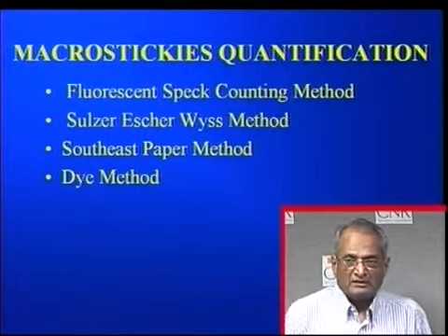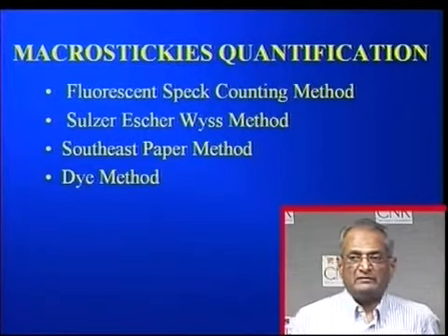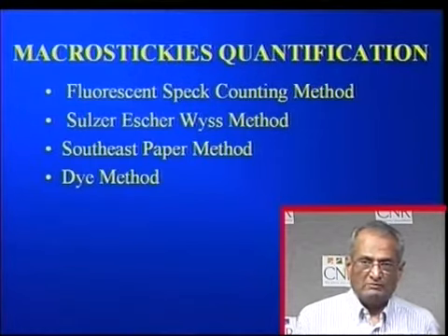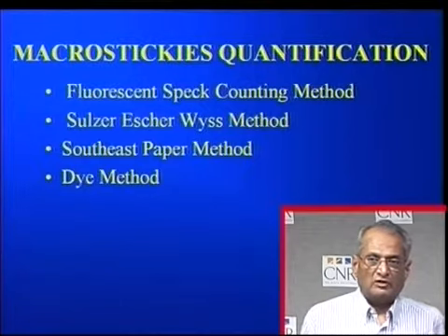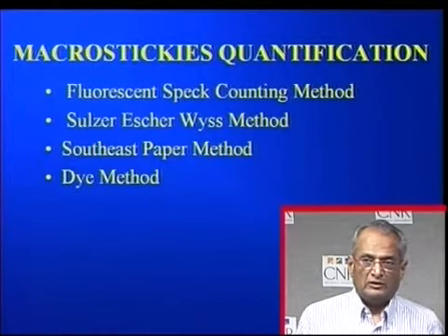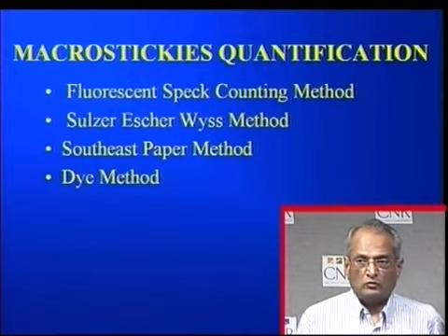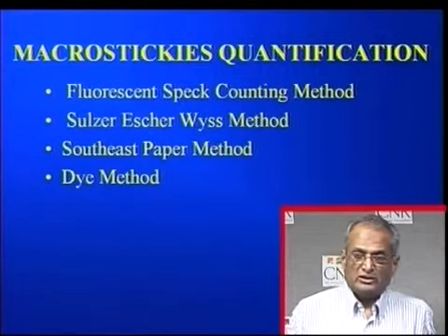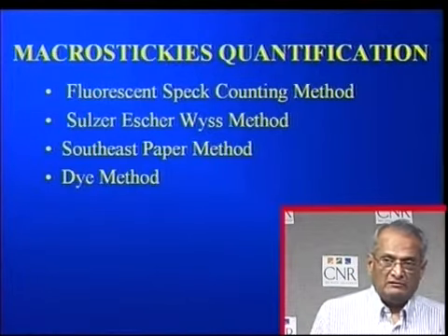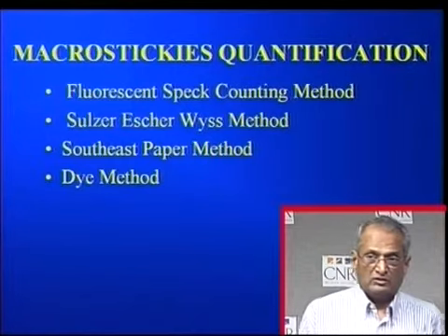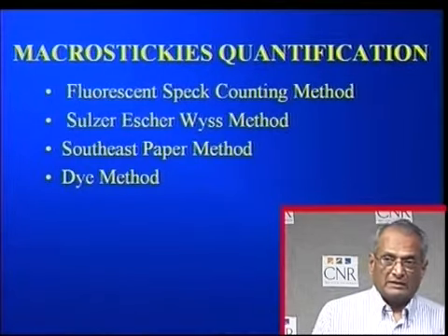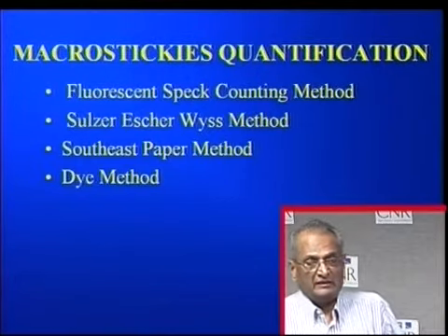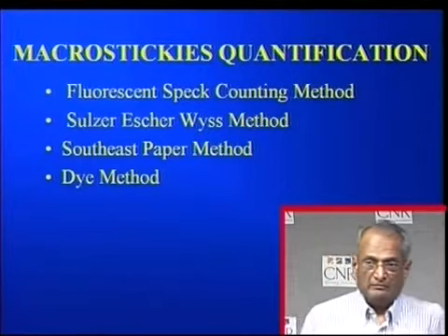There are many methods used for measuring the concentration of macro stickies, and we'll just go through some of the methods to give you the flavor of how different people use different approaches to measure the concentration of macro stickies. The Institute of Paper Chemistry in Appleton, while it was in Appleton, developed the fluorescent speck counting method. Some equipment suppliers, Sulzer and Jervis, developed their own method so that they can guarantee the performance of their equipment.